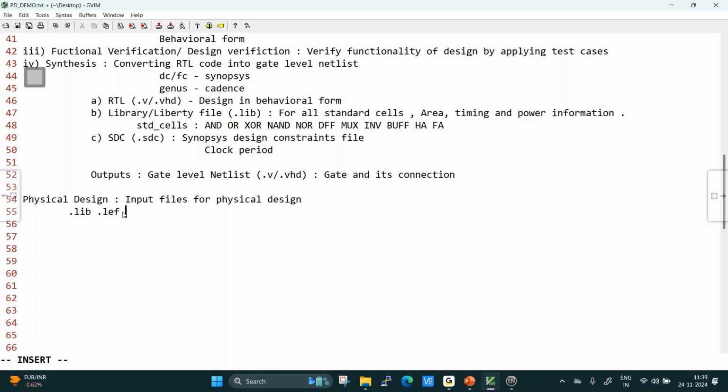So what is .tf? .tf is used in Synopsys, but we use tech lef, .tech.lef, in Cadence. Then what is the TLU+ file? What is netlist? Netlist I've already explained, right? Netlist, UPF, scanDef, MCMM file. All these files we'll discuss first: why we use them and what they contain. We'll open each file and discuss its content.